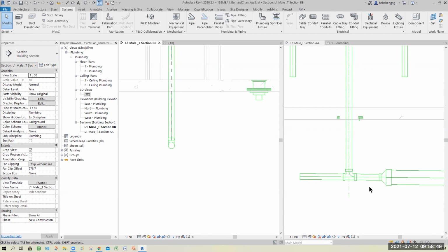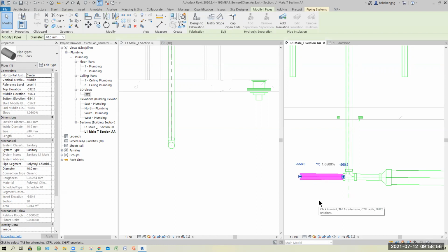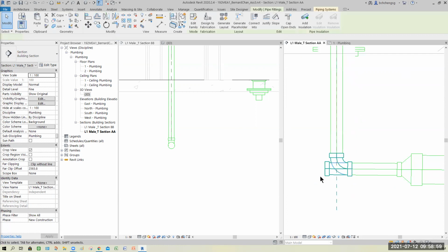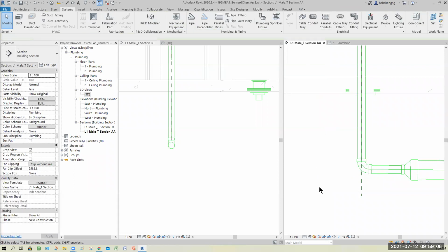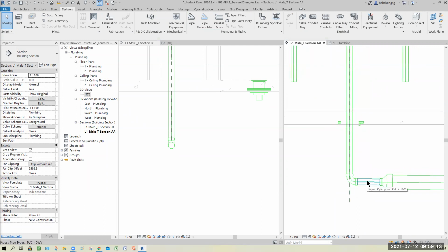But of course, sometimes it becomes like too many pipe sizes. So it depends. All right. So done. No change. Delete this away. And of course, here, remove your connecting. Unless you want to cater for expansions and so on. Okay. So if you decide to change this in between pipe, maybe bigger, I'm okay also. Because the flow is supposed to be small, bigger, and bigger by right lah. But sometimes due to the cost, too many pipe sizes also create problems. Why? You have a lot of adapters, reducers, all these things.